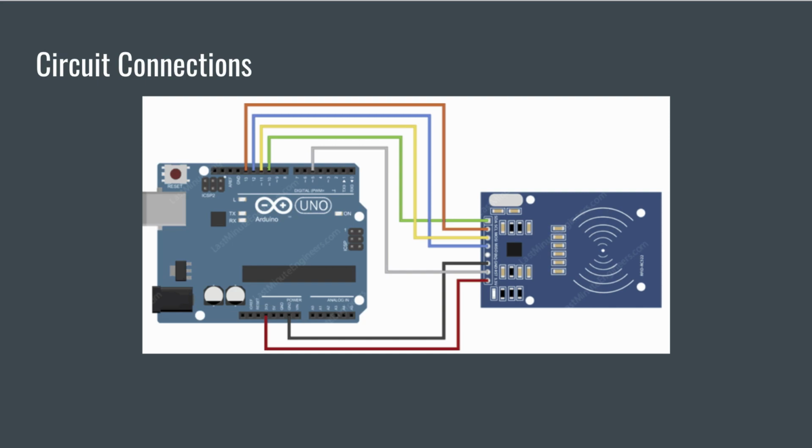IRQ is an interrupt pin that can alert the microcontroller when RFID tags come into the vicinity. The MISO pin acts as a master in slave out when the SPI interface is enabled. MOSI, or the master out slave in, is an SPI input to the RC522 module. SCK, or the serial clock, accepts clock pulses provided by the SPI bus master, that is the Arduino. SS pin acts as signal input when the SPI interface is enabled. This pin is usually marked by encasing the pin in a square so that it can be used as a reference for identifying the other pins.